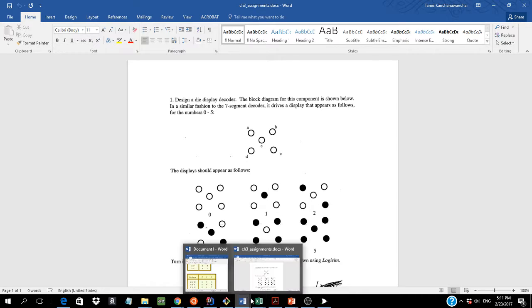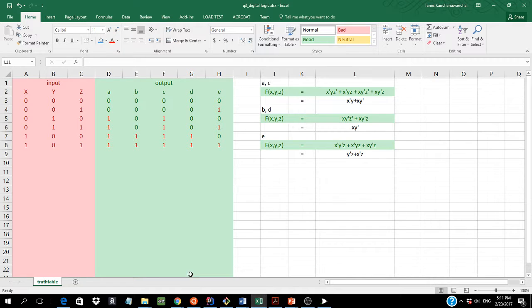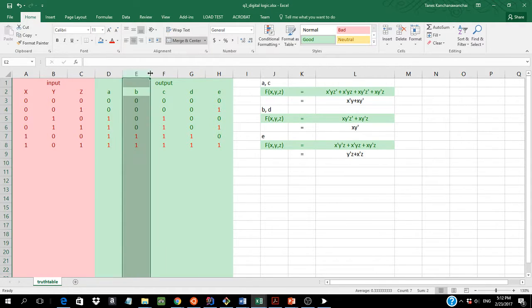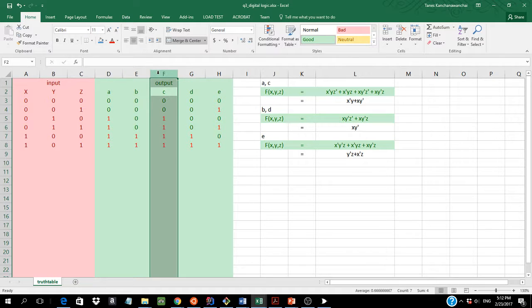So we start to construct the truth table. So 3 inputs, 5 outputs, right? And then we just decide whenever user makes 000, then we set all the outputs going to be like that, right? And then our output is going to be 1 and so on, right? This is the easy one, 0, 1, 2, 3, 4, 5. Then we have the dice that's going to light up, right? According to the inputs. From there, we're interested to just look at these are pretty much your expression for each output, right? That's Boolean expression.